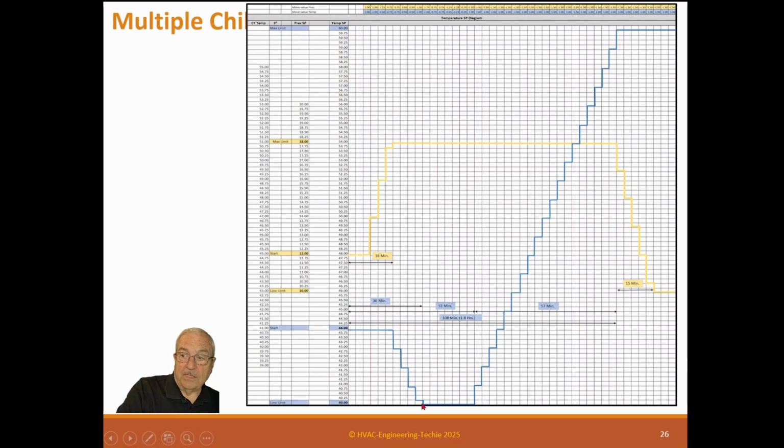So this sets to where it goes down to the 42 degrees, which is the minimum position. And it goes down and sets, well, that's 40 degrees, it goes down for a time. And then when it gets no more requests and it's time to start trimming, it will then set and trim the chill water temperature until it gets to maximum.